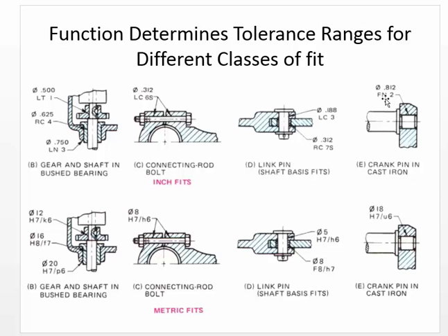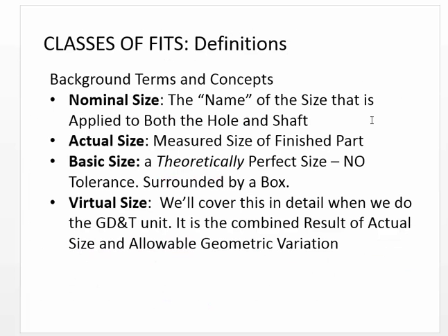And then we have a force interference fit. Force interference means you have a very, very strong interference. It's the biggest. Well, FN2 isn't quite the biggest, but the force interference fits require a significant amount of force, usually a hydraulic press, and at one level heating the parts and then pressing them together. And a force interference fit is meant to be more or less permanent. You don't normally take it apart, although it's possible in some cases to take them apart.